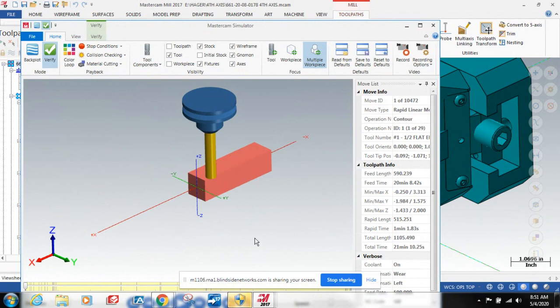No. All the plane really does is determine the angle that the tool is going to be entering from. If you have a diagonal angle, do you have to do a plane for that? Yes. Say you had 4 sides, but then there's a 45-degree angle; you'd create another plane at a 45-degree angle so that it would be perpendicular to the machine spindle.